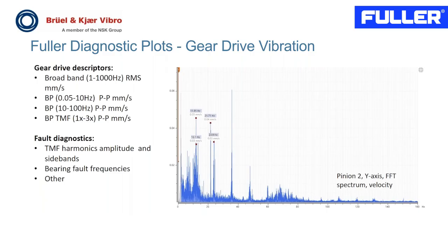In addition to the fault detection, there are also various tools available for vibration analysis, used by the FL Smith diagnostic team, such as the FFT plot, which we can see in this slide here. The FFT can be used for identifying the detected fault, determining its severity, and predicting the remaining useful life of the gear or bearing. This particular FFT spectrum is showing some peaks. The lower peaks basically correspond to the tooth meshing frequency for the pinion.